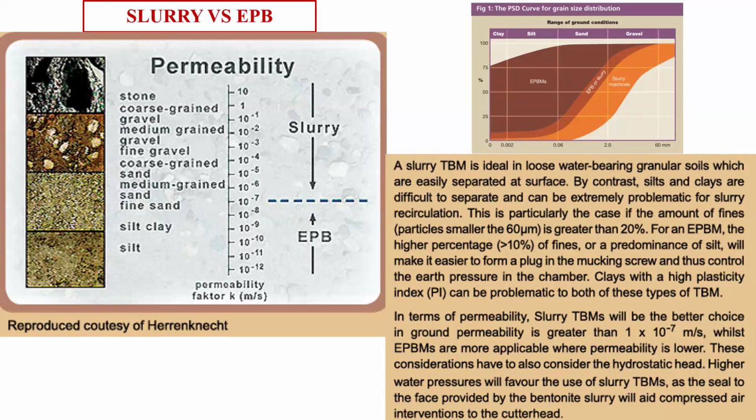Now, when you are installing the TBM and the TBM has to start, you have to push the TBM because the TBM does not get the thrust from the segments, as you have not installed them yet. Sufficient segments need to be installed first; otherwise, the TBM cannot get the desired thrust. So what we are doing is preparing a reaction frame.